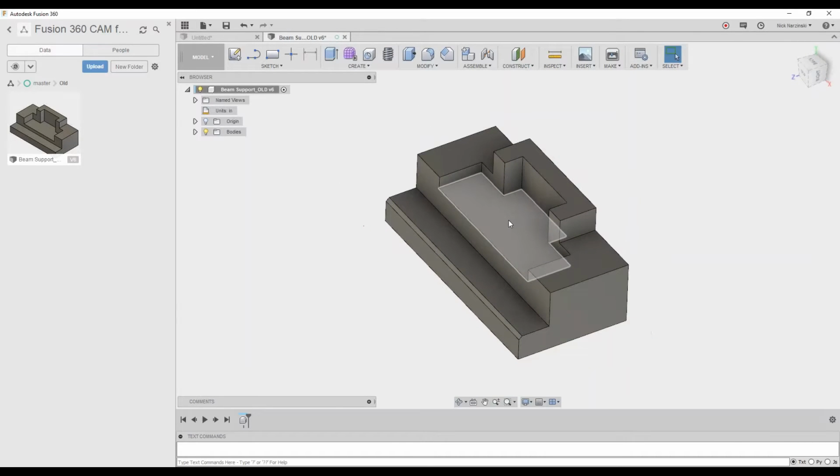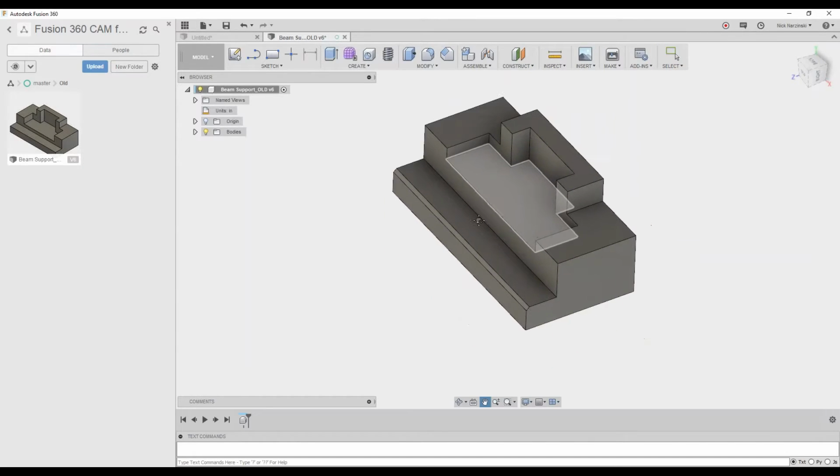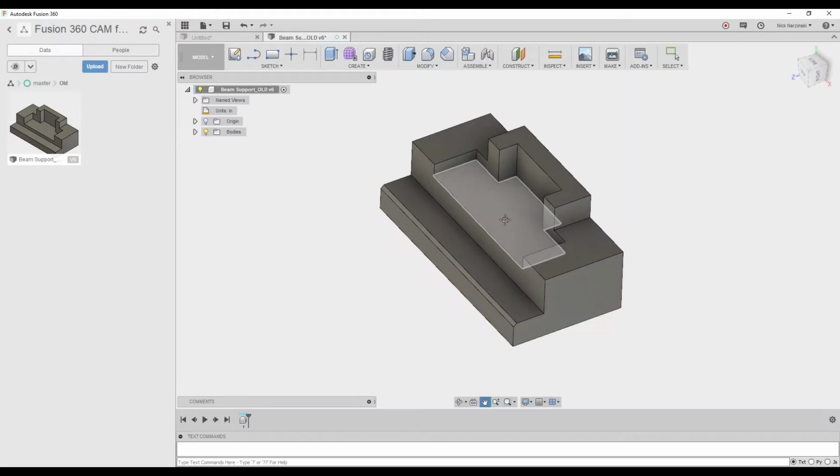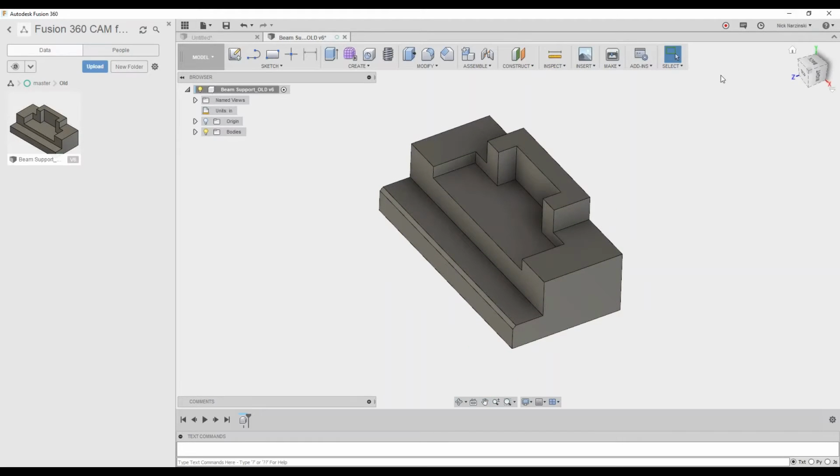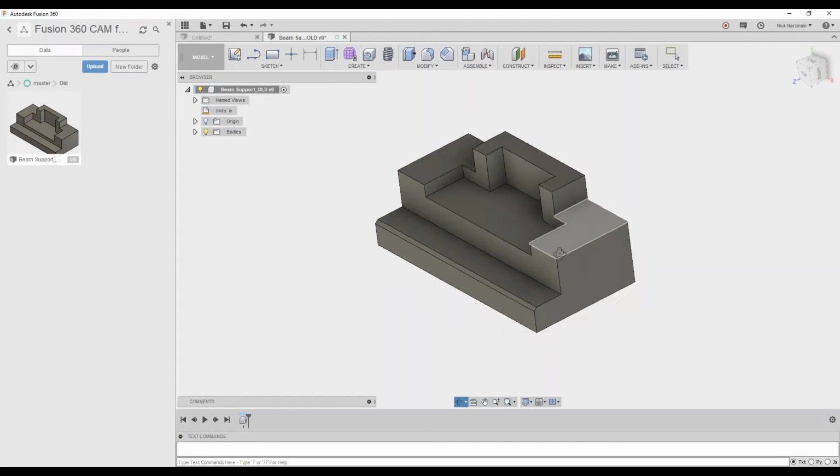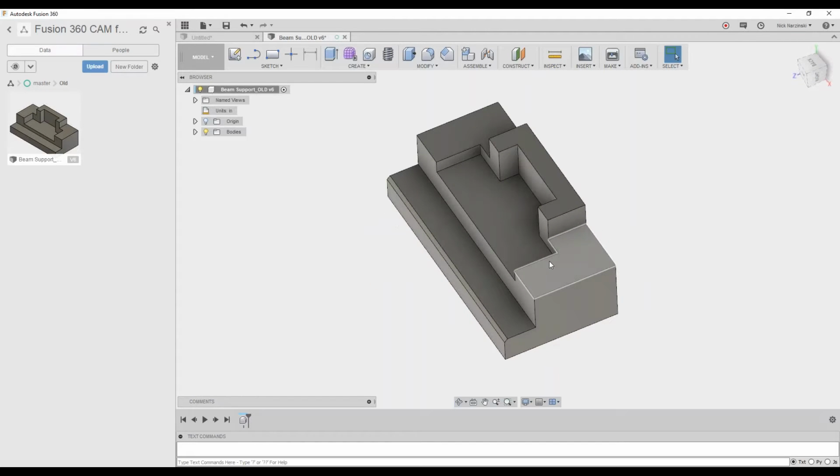Your zoom in, zoom out, just by rotating the wheel. If you hold down Control and hold your mouse wheel button down like a button, that does your pan. So by changing that, it will change your controls with the mouse and the keyboard to be the same as SolidWorks. So in that aspect, it'll be a very seamless transition to manipulating the view of your model.